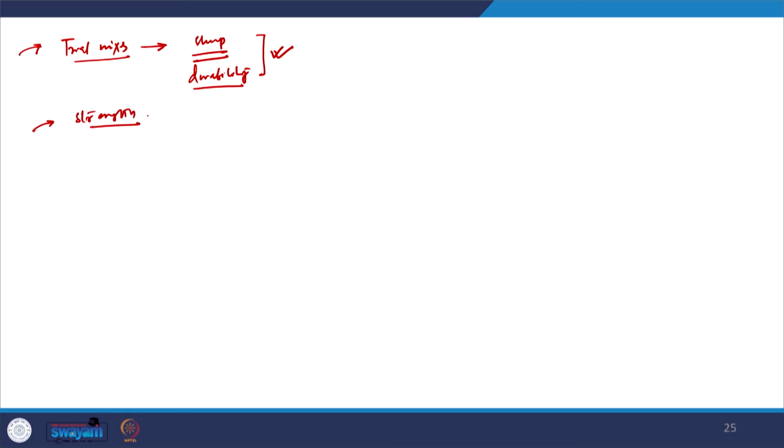If the initial proportion which you got does not give you the required slump or durability, some adjustments need to be made, and accordingly the values will change. And once you satisfy all the requirements, keeping in consideration the different checks of maximum and minimum values, we will further proceed to make samples at the chosen water cement ratio and plus minus 10% water cement ratio.